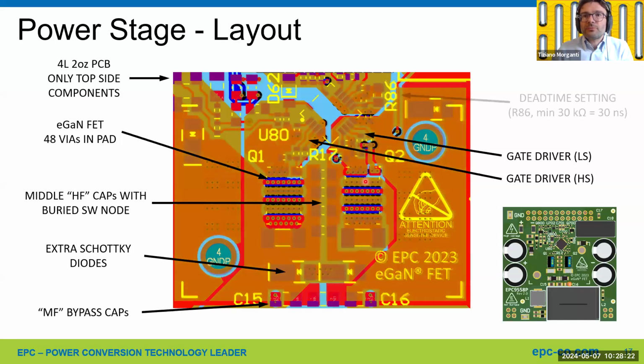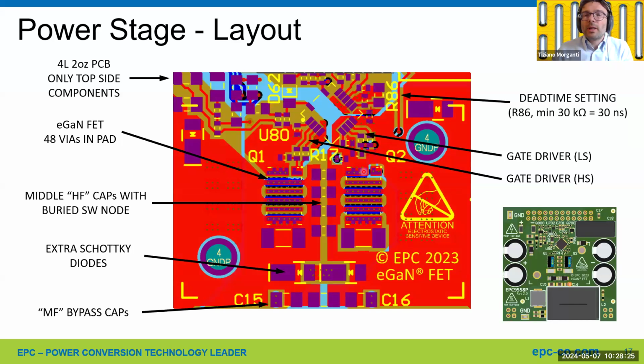Then we return to the source of the low side FET, and we close the loop directly on the high frequency capacitor. So you can see the commutation loop is very short, it's wide, and it's implemented in the 2 upper layers of the board, which are spaced by 0.2 millimeters. So the power loop inductance in this way is quite limited.